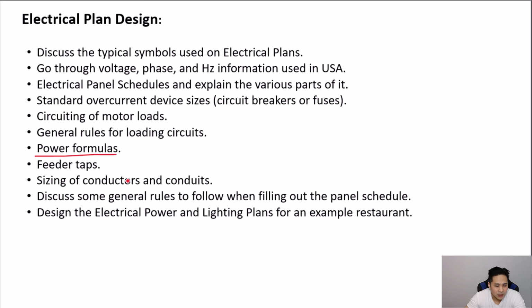Then we'll talk about the various power formulas that are for different voltages. So for a single phase, the power formula will be different from a three-phase circuit. We'll then talk about feeder taps, what it is and how to size them.